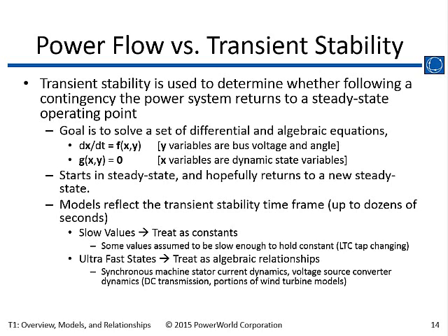The model reflects the transient stability time frame, and in doing this, there are embedded assumptions, and you do have to understand, at least to some extent, the embedded assumptions. PowerWorld uses the same embedded assumptions that other packages like PSLF use. So the ultra-fast states, like the stator transients on the machine, you may or may not have heard of that. You may have done a lot of transient stability runs and never heard about stator transients. That's because they're treated as algebraic relationships.